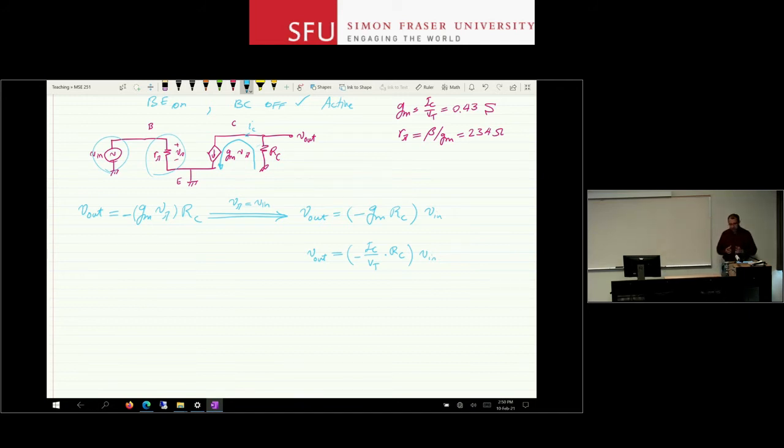you will see the value as soon as I start to add a couple of other transistors here and there. If I take the small signal route, I'm doing a small signal analysis. It's a linear analysis. It's fairly easy. You just write a bunch of KVLs and KCLs and make your system of equations and solve it. If you are going to do the large signal analysis, life can be more complicated, right? And a lot of those systems of equations you cannot really solve easily. A computer can do it, but an engineer that is going to do this analysis in the field cannot.